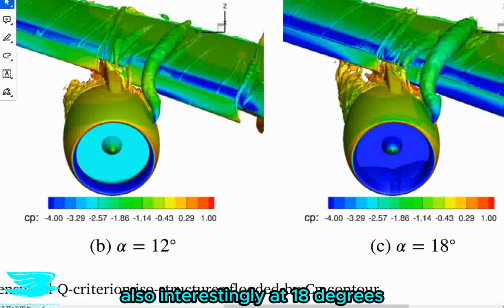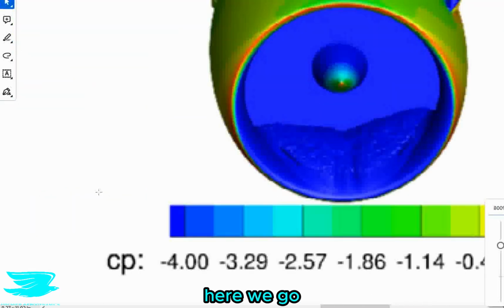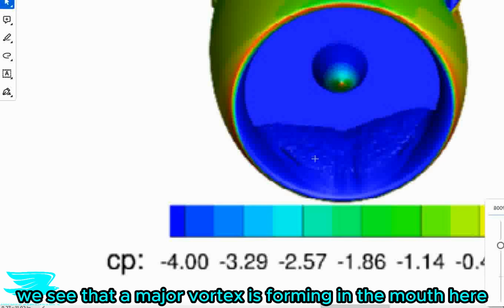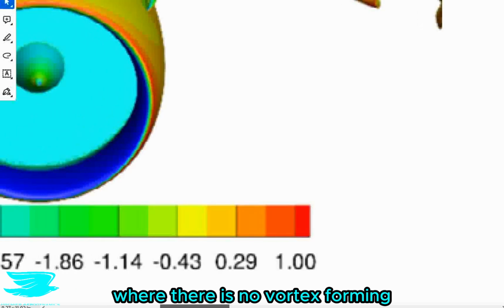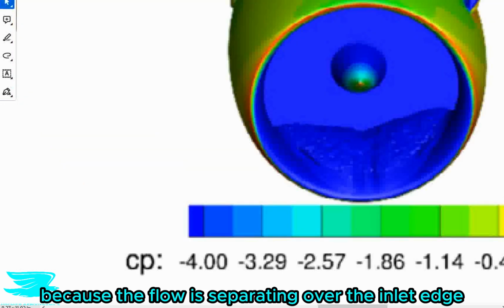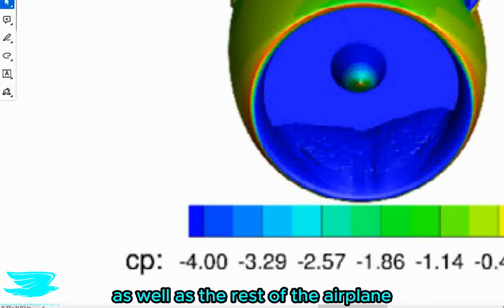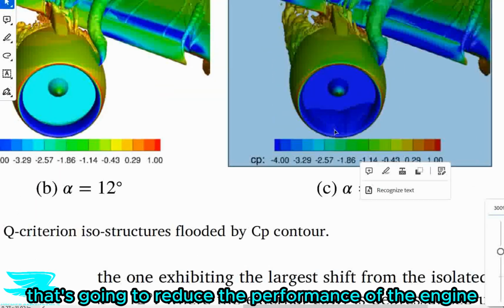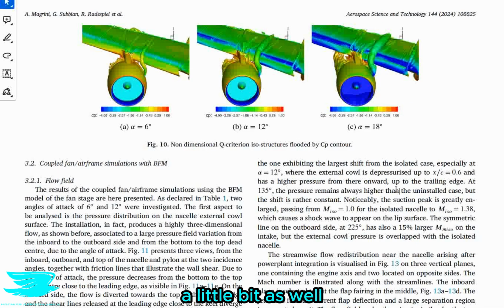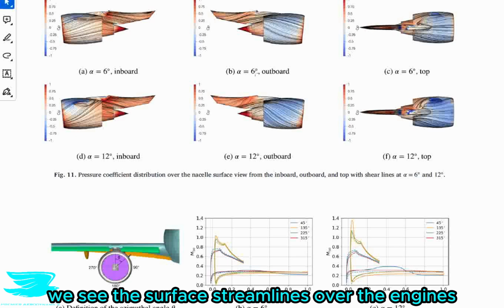Also, interestingly, at 18 degrees, if we zoom into the inlet a little bit more, here we go, we see that a major vortex is forming in the mouth here compared to the other regions where there is no vortex forming. That is because the flow is separating over the inlet edge and creating the vortex here, and that's because the engine is now at quite a high angle of attack as well with the rest of the airplane. So we're getting flow separation here, and that's going to reduce the performance of the engine a little bit as well.